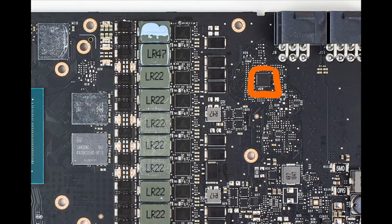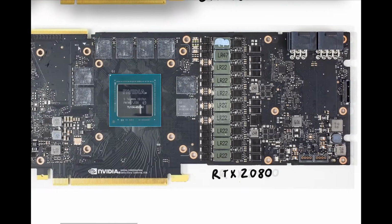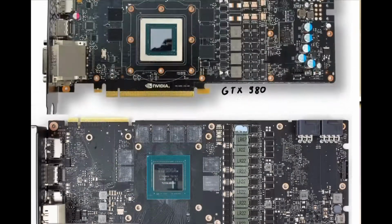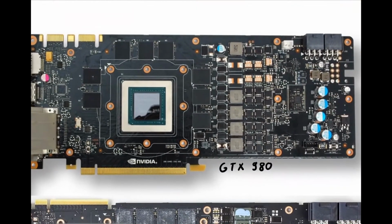There will be something written like UP9512. That's pretty much the standard PWM controller for NVIDIA's 20 series. For the 10 series it was the UP9511, and this card has its PWM controller right over here.